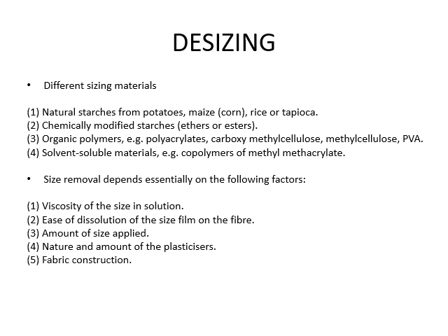Then fabric construction. If it is an open type of fabric, with fewer ends per inch and fewer picks per inch, then penetration of desizing chemical will be better. Again, if the thickness or construction of the fabric is too tight, then penetration of that desizing chemical is more difficult. Definitely desizing time should be increased.